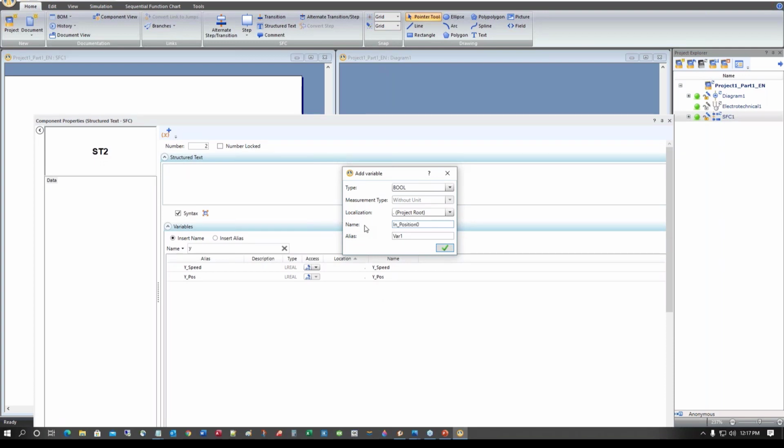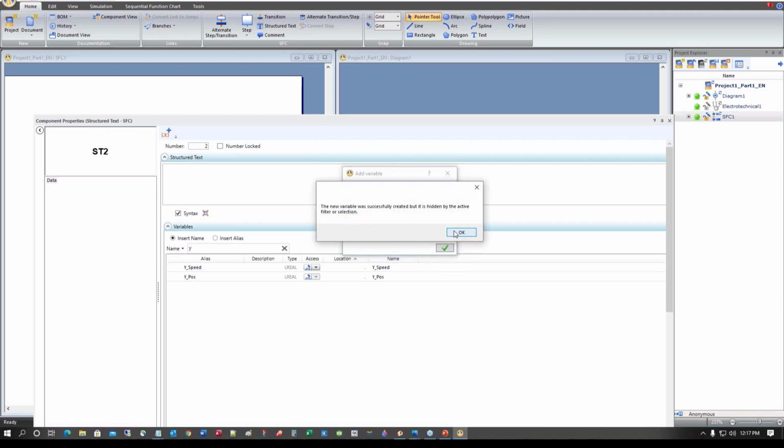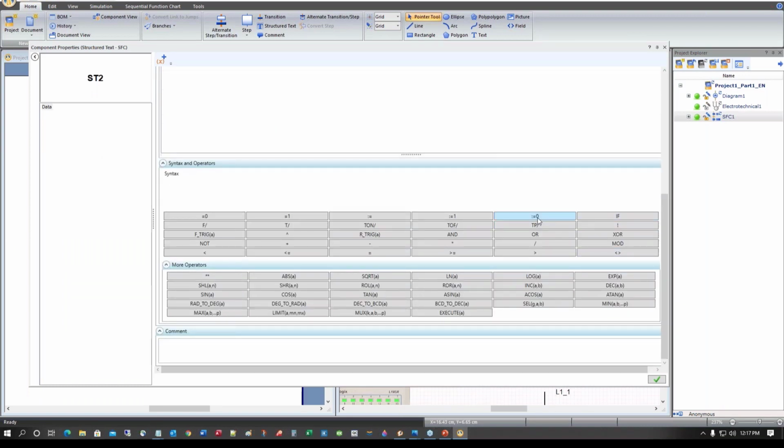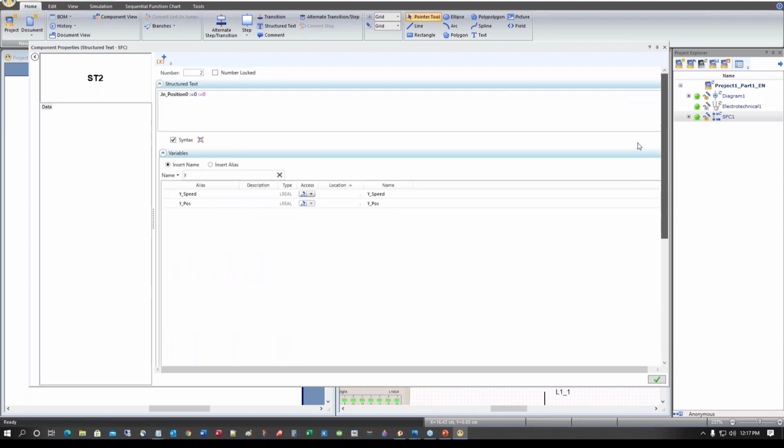This is like in real life, with boxes you usually put a sensor like a photocell or a proximity sensor that, once the box is located at the right position, will trigger a 1 to tell you that the box is in position, it's sitting in this position. So I'm creating here a variable for that, in position 0. And to simulate it, this is a Boolean, so I'm going to say it's 0 equals 0.